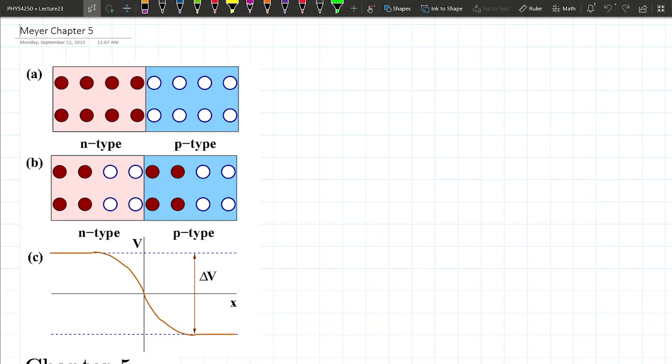And then when they get stuck together, what happens is that the n-type doesn't have an extra electron, it's not charged, right? But there's a tendency for the electrons from the n-type semiconductor to migrate to the p-type semiconductor. This is called the donor, and this is called the acceptor also, okay? And this creates an electric field between them, because after you sandwich them together, this side becomes slightly negatively charged, this side becomes slightly positively charged.